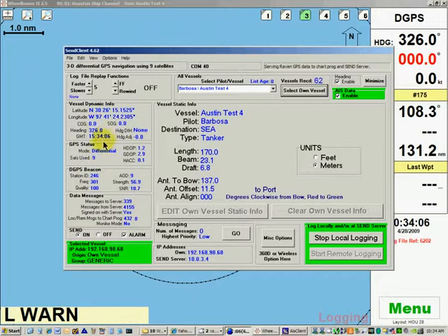And then moving on down, we have a GPS status. The GPS receiver is in differential mode. That's the local GPS receiver, using 9 satellites, HDOP, the GDOP. Here's a parameter called HACC, which stands for horizontal accuracy, and it is unitless, an indicator of RFI or multipath. Typically, this number being under 1 indicates there isn't any RFI or multipath. If that number was above 15, then the system would generate a warning. Now, this is something that's unique to the Raven system.